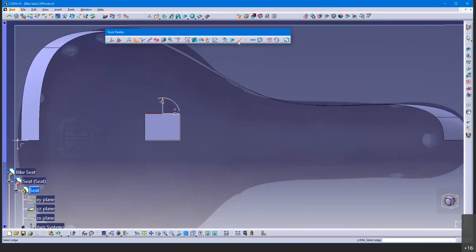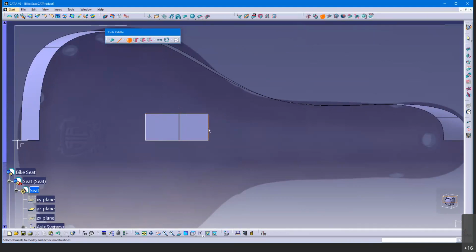So what I'm going to do is come in and use the extrusion tool. This is not the same as this extrude tool. It's this extrusion tool, on this styling surface toolbar. So I'm going to do an extrusion, and what needs to be selected over here is this edge extrusion and this fill. So notice what happens when I do this. There's 1, there's 3, and I said what, 4? I hope that's enough. So there's my 4.